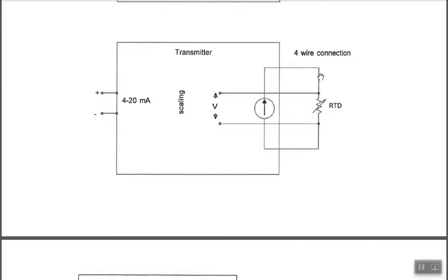It actually doesn't matter which wire you use here. For example, I think the ones we have in the lab, you might have 2 white wires and 2 red wires. And you don't need to waste time trying to distinguish which red wire you should use to carry current to the RTD and which white wire or which wire is which. It helps save you time if you just realize right out of the box that the 2 white wires are identical. They're going to the exact same place. And the 2 red wires are going to the exact same place.